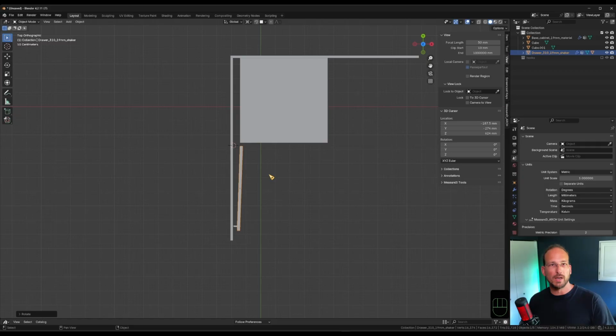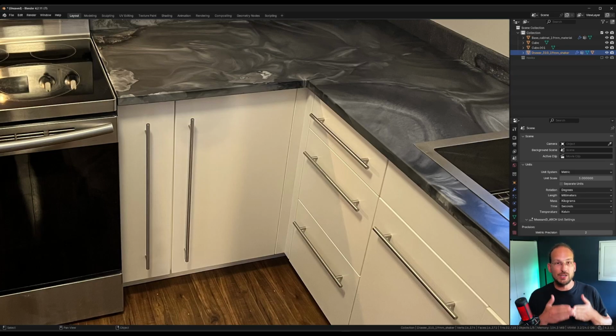It also depends on what kind of hinge you use. A lot of the European style hinges range from anywhere between 92 and 110 degrees. There are different ones also that can open up to 170 degrees, but those are the standard hinges. So you just want to make sure that you can open the door at least 90 degrees. And the same goes for inside corners if you have two cabinets running into each other. In those positions, I usually just go for plain 50 millimeters in both directions, and that way I avoid something like this.